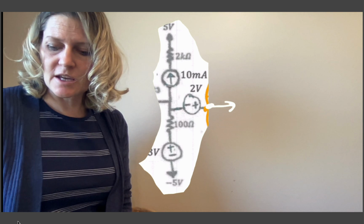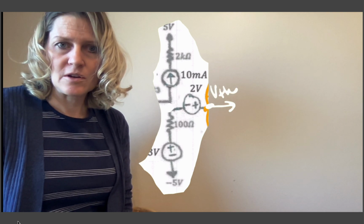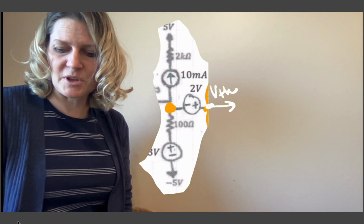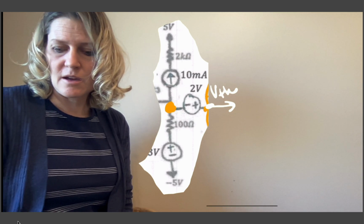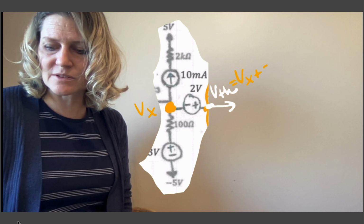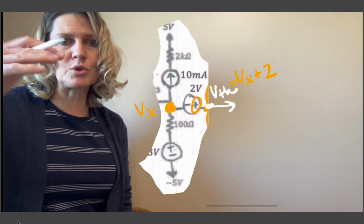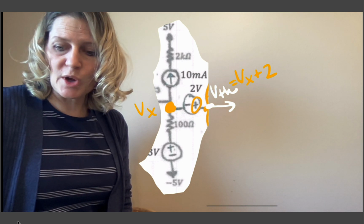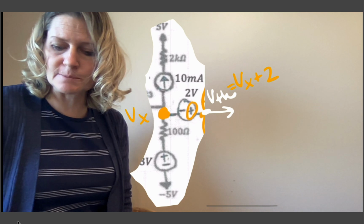VTH is going to be at the end of this. If I can find the voltage at the node here, which looks like an open, and I call that Vx, then VTH will be Vx plus 2 volts. So you would go across that. Vx is one voltage and then another plus 2 volts to get to VTH. I can do a node voltage, or I can do a voltage loop here.